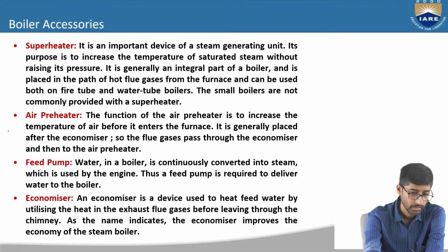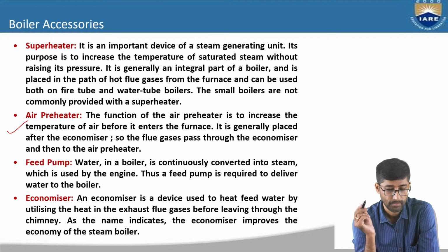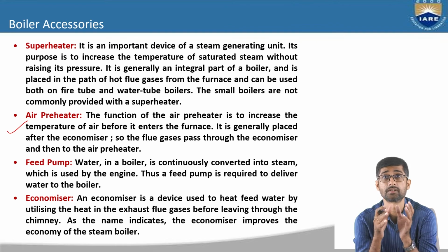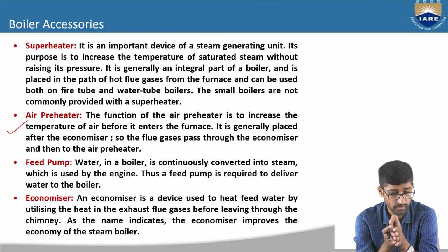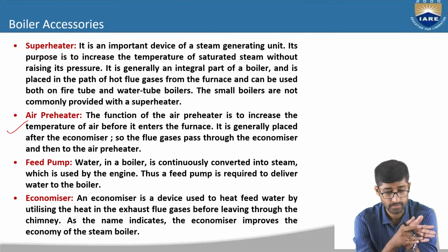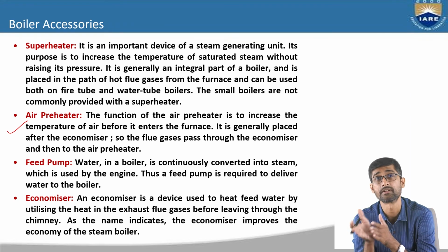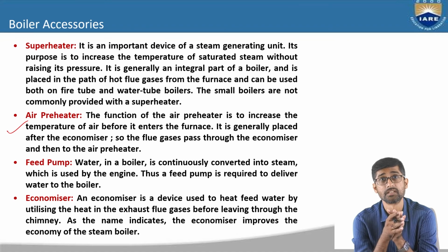Next, air preheater. The function of the air preheater of the boiler is to increase the temperature of air before it enters the furnace. It is generally placed after the economizer. So the flue gases pass through the economizer and then to the air preheater. Right.